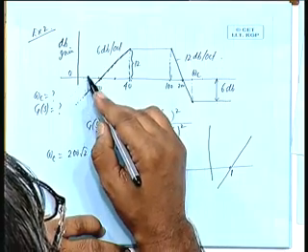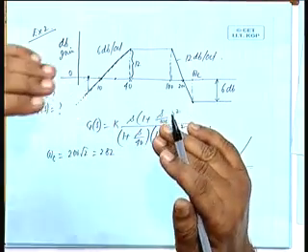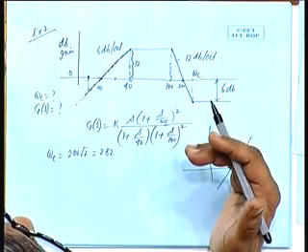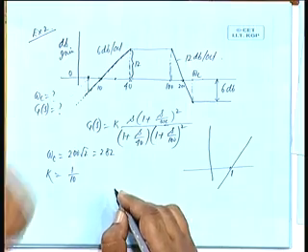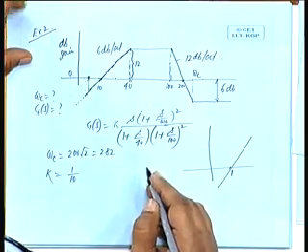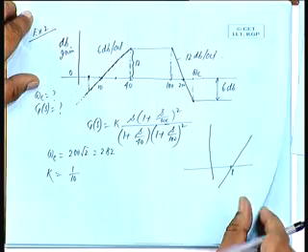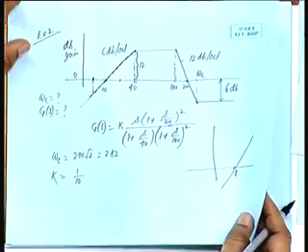So, you have given a boost in the negative direction by 20 dB. So, how much is k? How much is k? 20 log of k is minus 20. So, k equal to 1 by 10, log of 10 is 1, so minus 1 means 1 by 10. So, k is 1 by 10, is that okay? So, this will be the transfer function. Now, another problem on Bode plot.